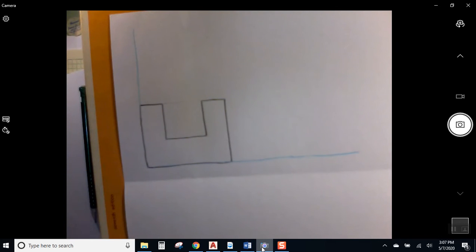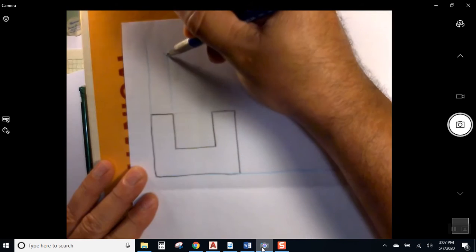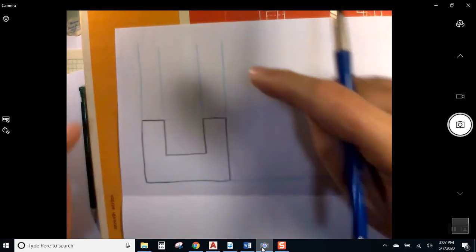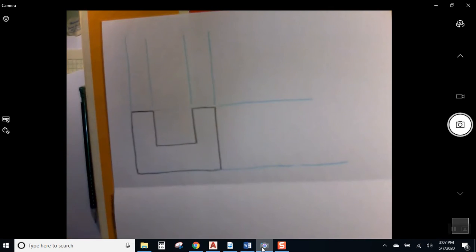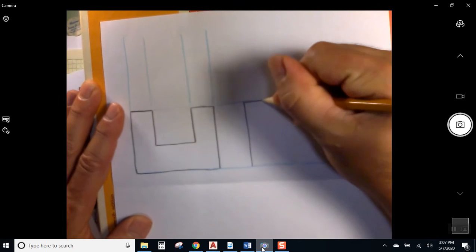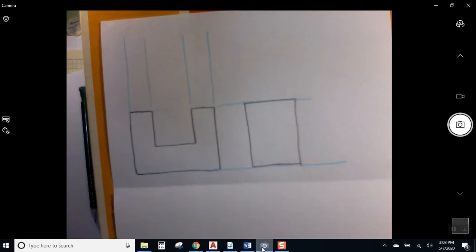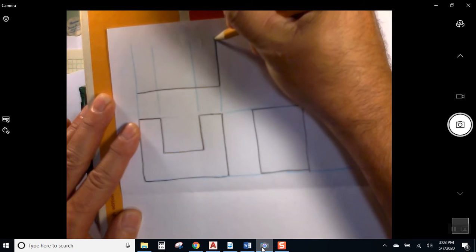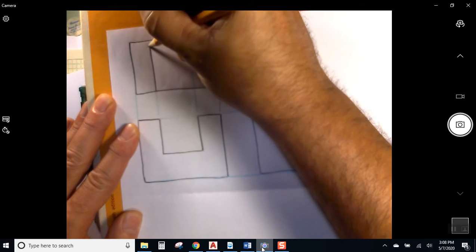Right, so I think by now you know the rule. The rule is project the corners up to make the top view. That saves us some work for measuring width for the top. Project the corners to the side to make the side view. And you probably remember what shape there was in the side view, and what shape we were looking at in the top view, or shapes.